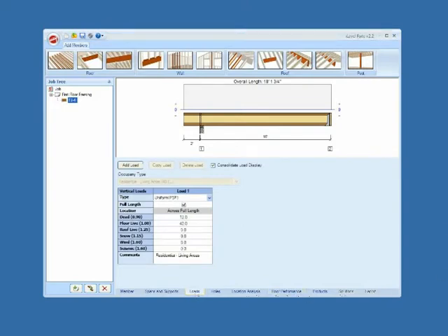So next we go to the Loads tab. And there's a couple different ways to input loads. You want to be very careful and pay attention to the type of load, the units specifically, that you're inputting here. So we have this residential living area. This is our floor load. So our on-center spacing is going to determine how much load gets applied to each joist. So we'll notice that our load is in pounds per square foot, so it'll be loaded up appropriately.